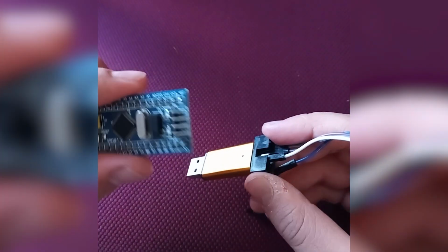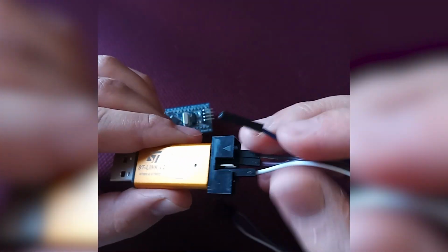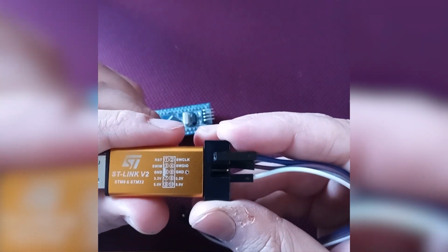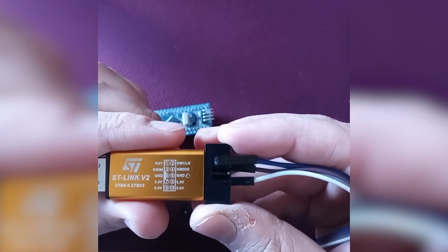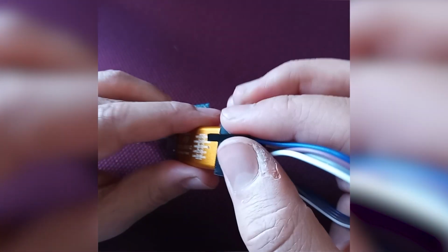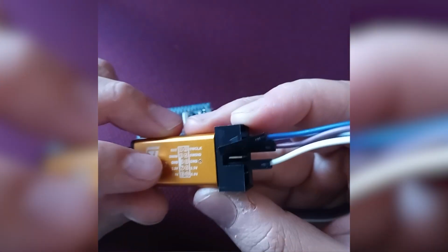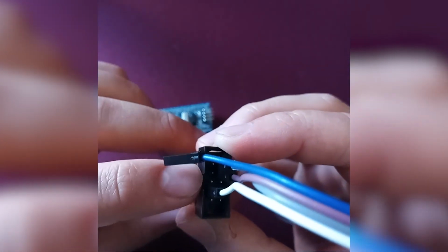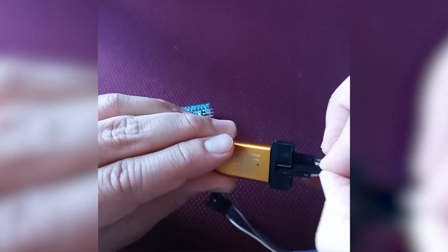The last one was GND. And I have to connect this blue jumper to GND. And the pins that provide GND are 5 or 6, it doesn't matter. I pick pin number 5. It is this one. As you can see, 5 is near this line, here on this part of the programmer. So I connect that.